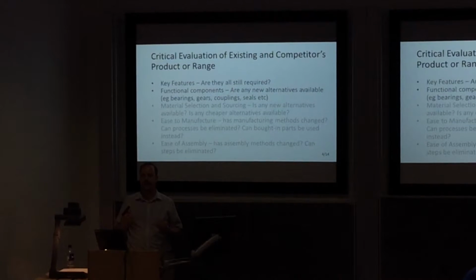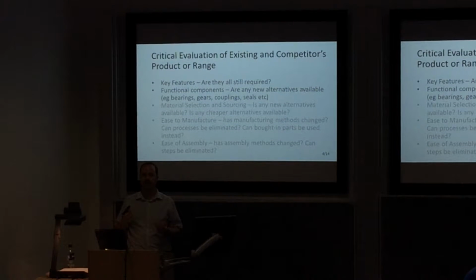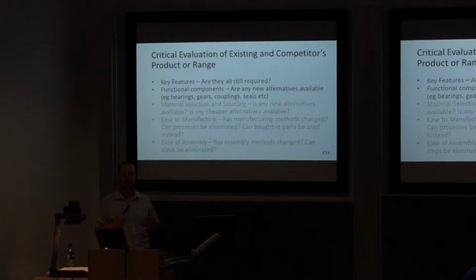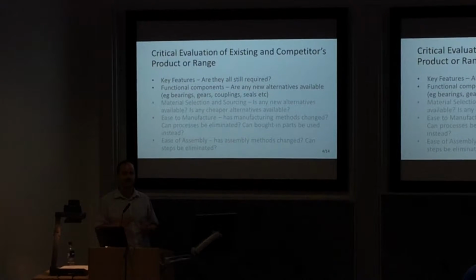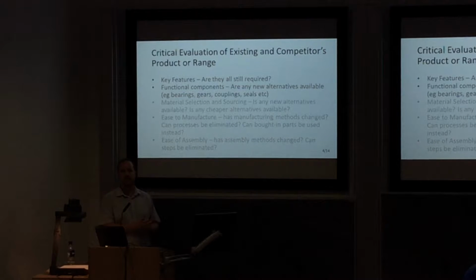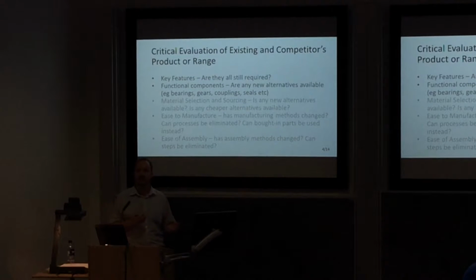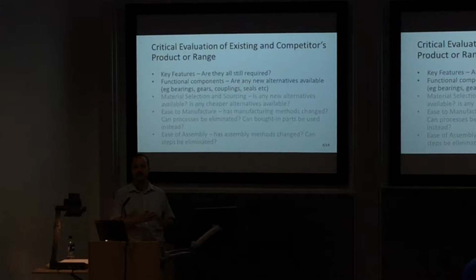Very common back 20, 30, 40, 50 years ago. They actually used to use asbestos impregnated ropes because it had very good sealing properties and heat resisting properties. That asbestos is now not allowed, and packed glands is a very difficult way of assembling a mechanical seal. So the industry has moved on.